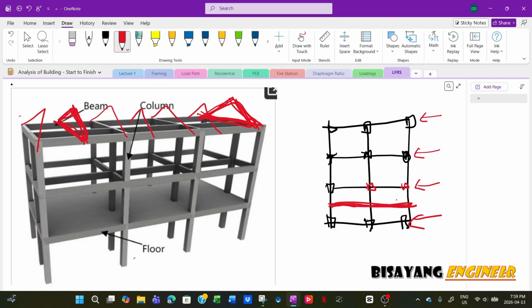If you have a truss in the middle, then you apply the load also at mid-span, because in reality, if a truss transfers the load through the beam at mid-span, then that beam has to resist that horizontal load.